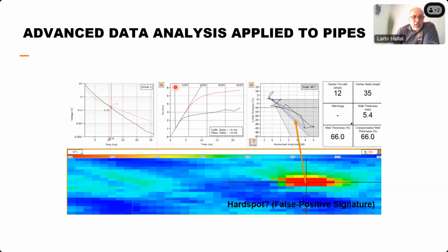Looking at the Tau-Scan, you identify directly at the beginning of the signal some saturation. Even if the plateau looks good and the bending region looks good, there is definitely something wrong with this saturated signal. And looking at the PermTool, all our points are plotted in the dark gray region. This is typical of a false positive, so there's no corrosion here.